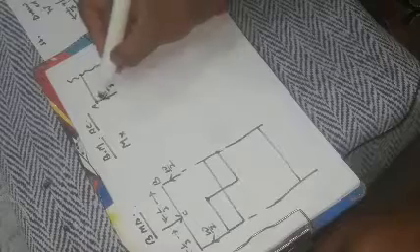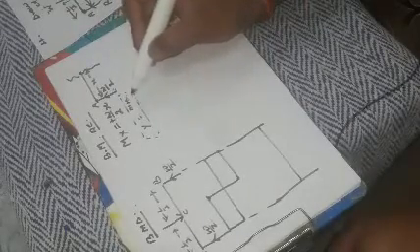W by 2, and here is the section, this distance is x. Now there is only one force, I have to take the moment of this force about this cross section, and this is an upward force, so the moment of this force is positive. Then the bending moment for this section is W by 2 into x. Here the power of x is 1, and it is analogous with the equation y equal to mx, that is the equation of an inclined line, right? So this is the bending moment value for a given section.